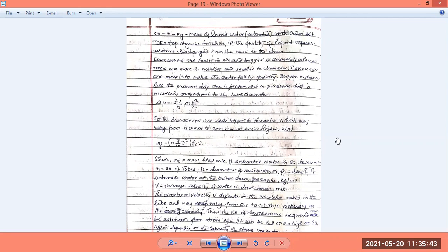So we have three terms: m, the mass of the saturated water flowing through the downcomer-riser circuit during a certain time, divided by the mass of the gas coming out of the drum. The mass m is equal to the mass of the gas going out plus the mass of the water that remains as liquid.